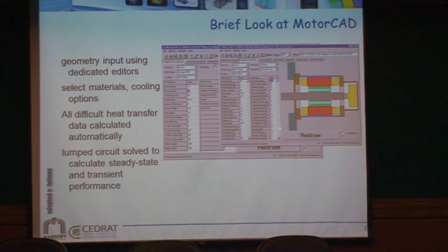You can see here the motor can be mounted or not mounted. We have some information about feedback that doesn't exist in Speed, and other things of this kind. And eventually you'll see fins and other things like this. So here we have things like the housing lengths. We have also the shaft extension, because the shaft is important as a thermal sink. Everything that actually brings a thermal option to the device. So the geometry is done using those dedicated inputs.